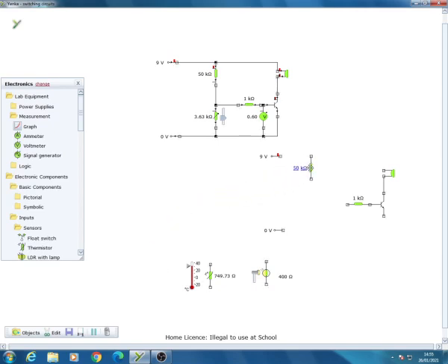I'll always have a large resistor so that I get something called a potential divider. And this resistor, first off, we're going to attach as we have in the top circuit. The bottom bit down here is going to attach straight to 0 volts. Now this won't go on, the buzzer won't go on because this switch is off. The transistor is off because I don't have 0.7 volts across the base input here. Now what I can do, if I want to detect light, I can use this.